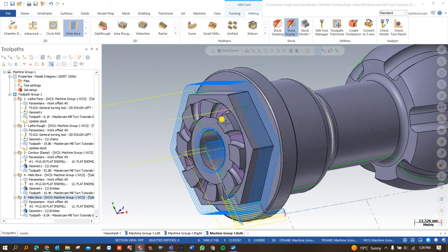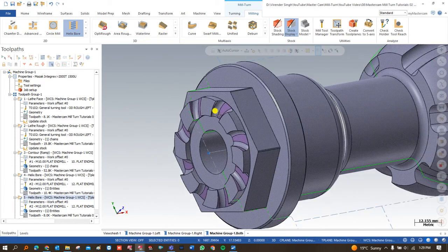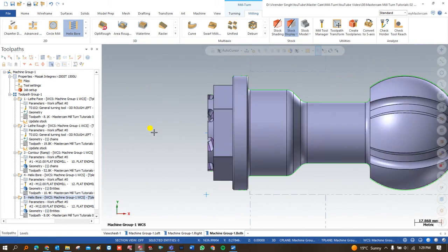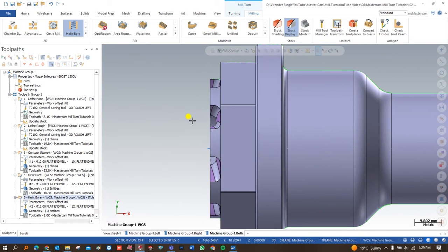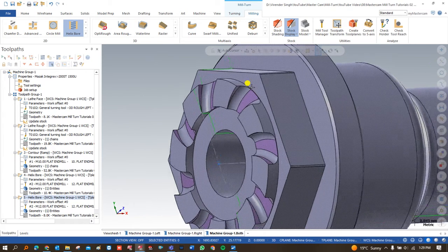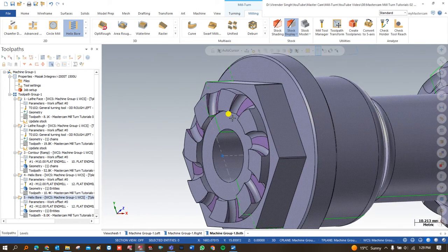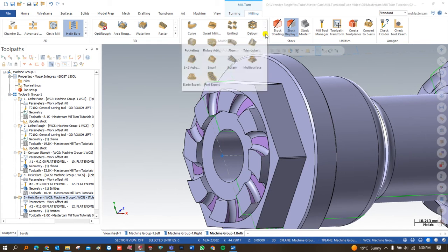So now we need to create a toolpath for removing material from one area of that component. So we have to see which toolpath we can perform. We can't perform any toolpath from the Mill 3D or Mill 2D because that has a profile and that's a little different. So in that condition, when we are talking about Mill-Turn, Mill-Turn has access to all the lathe, milling and multi-axis toolpaths. So we can choose a multi-axis toolpath.